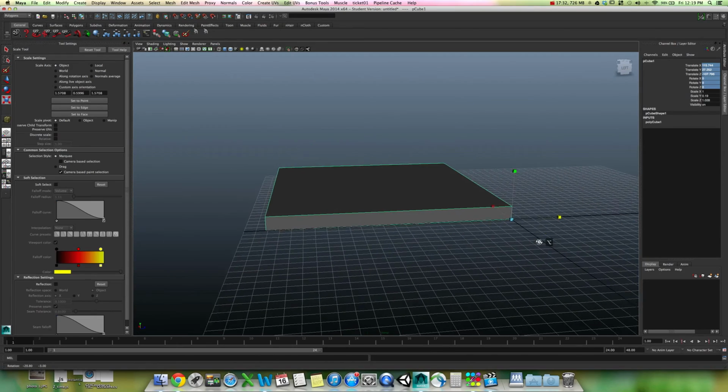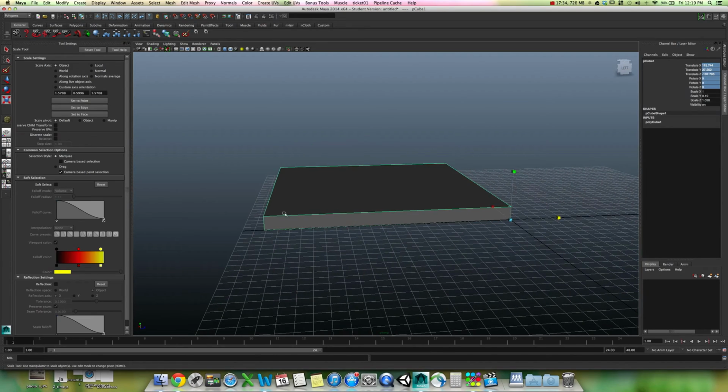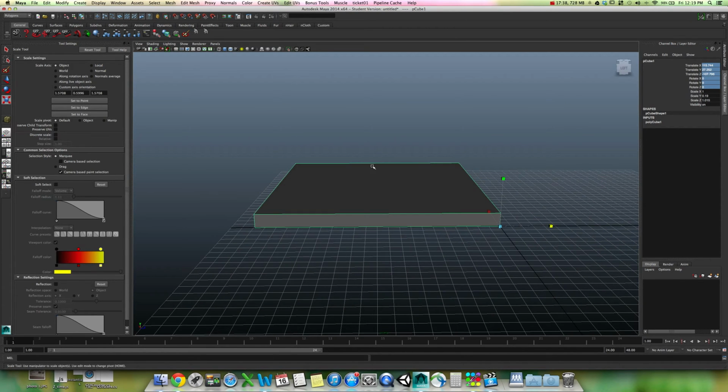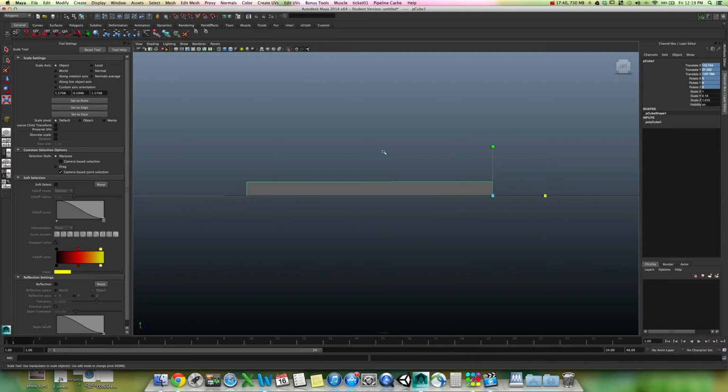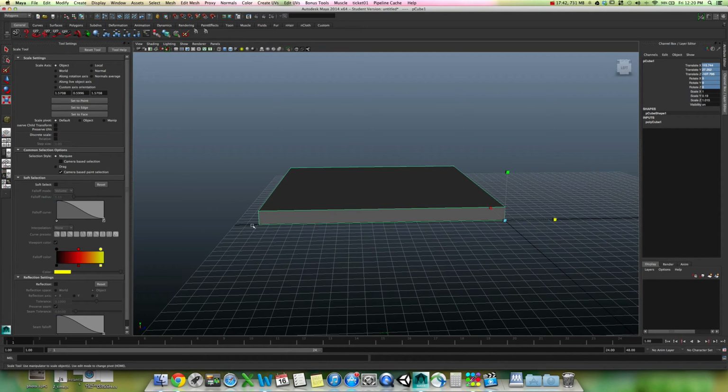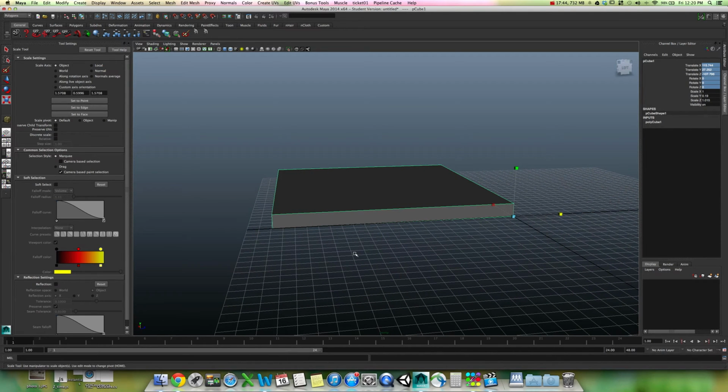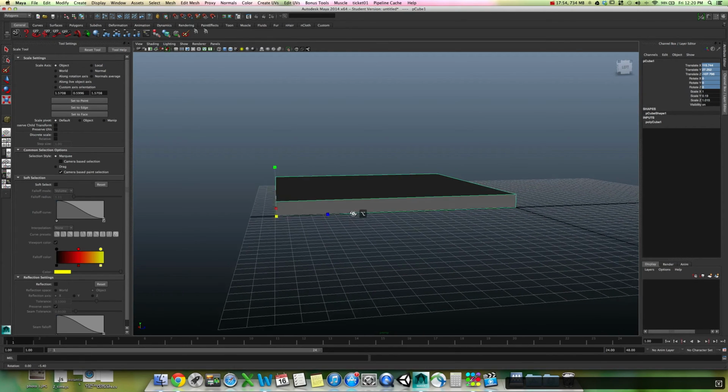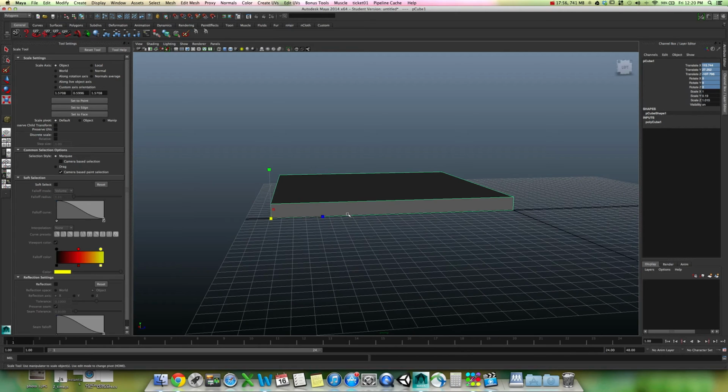And I can scale this backwards from this point in space. Now what I'm going to do here is move this pivot point back a little bit. The reason I'm moving it back is because I'm going to build a staircase, and we're going to keep iterating these stairs going up and up based on this point in space back here. So once again, I'm going to hit function left arrow, hold my V key down, and we'll just snap it to the rear left, and then get out of our pivot mode. Now why are we doing this? Because I'll show you why.